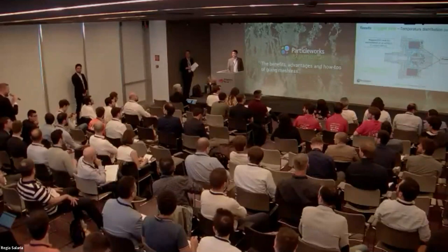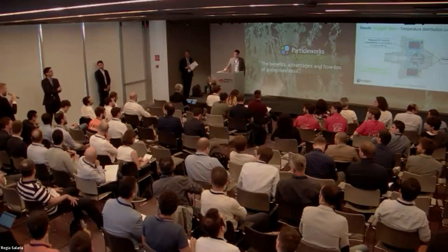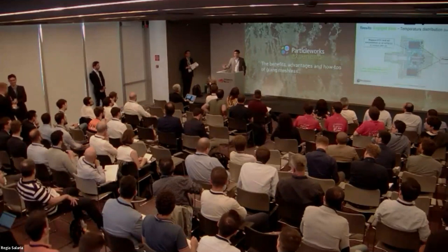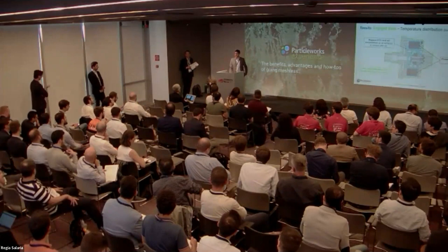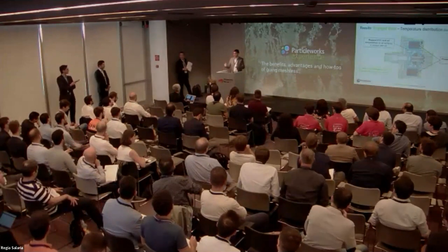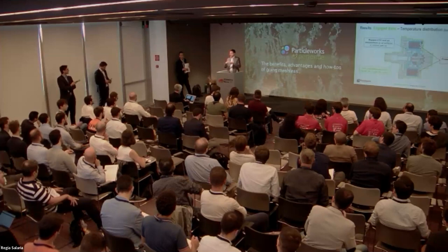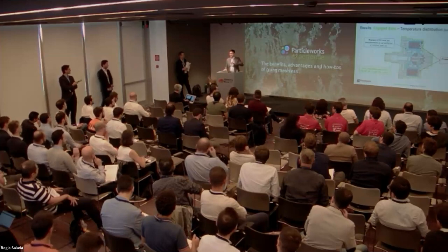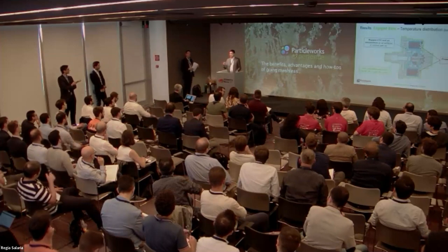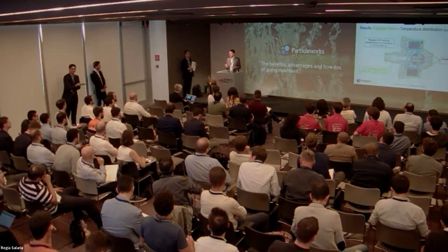Thank you for the presentation. I have a technical question. If you run the simulation on multi-GPU, do you always connect the GPU cards by NVLink? Okay, so you can do it, but it's not mandatory. If the GPU cards are on the same computational node, you can also use a standard connection. Of course, if you have NVLink, probably the connection is faster. Maybe we can ask the developer, but probably it's faster. But also without any NVLink, the scalability is pretty good. When you double the GPUs, you save more or less 40%, 45% of the simulation time without NVLink. I never tested it, but I think at least for me, it's good.